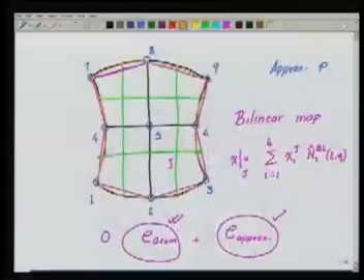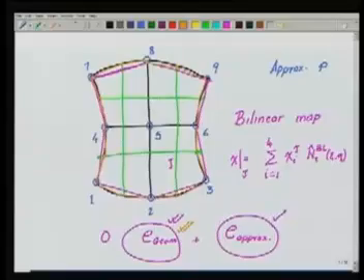But here we have also improved the representation of the geometry, and so the representation of the geometry is better and we can get better solutions. Now the question is, do we have to refine the mesh? Because when you refine the mesh, the cost of the computation goes up, the number of unknowns goes up. So why not control the error in the representation of the geometry by doing a better representation of the geometry?